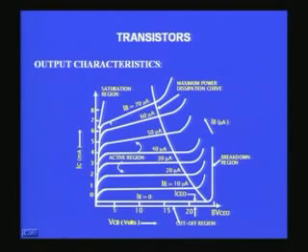You would find this will be the family of characteristics that you will obtain for different values of IB, the corresponding values of VCE and IC. This should be VCE, not VCB.